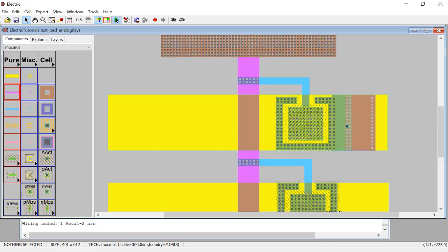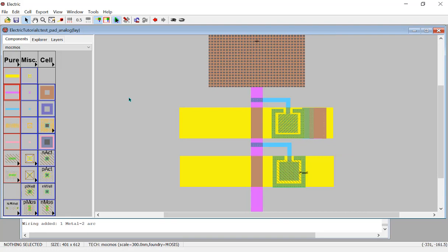and we want to do the same thing here, but we do not need a metal 1 to metal 3 connect, because this is just directly going to, if you have another pad over here on the other side, you just need a metal 3 to metal 3 connector, right? So you can directly just use this one. I will just copy and paste that guy, so that I make sure they're consistent. And keep using the same part.